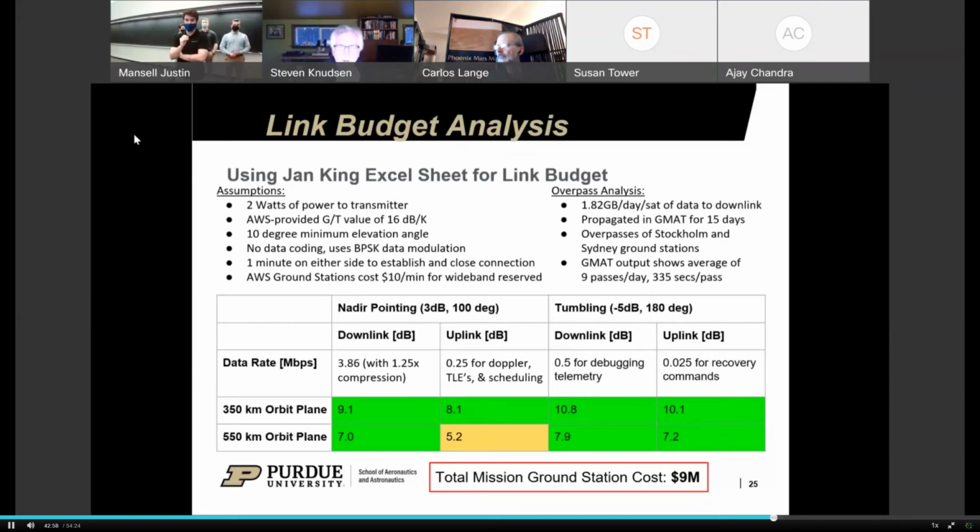There were various schemes that we didn't implement but thought about to reduce that. Plus, it was a worst case assumption that all the data had to come down, with no smarts about it. So it was worst case, and it did work fine. You wouldn't necessarily want to do it for your uplink, because something like LDPC is iterative in the decoding phase, and that is much slower. But on the ground, you can process it offline. The decoding doesn't cost you anything.